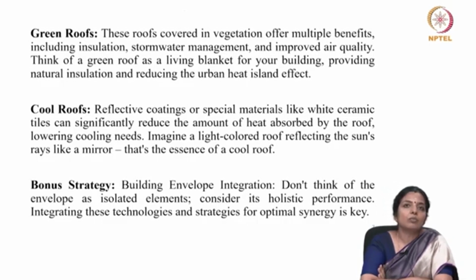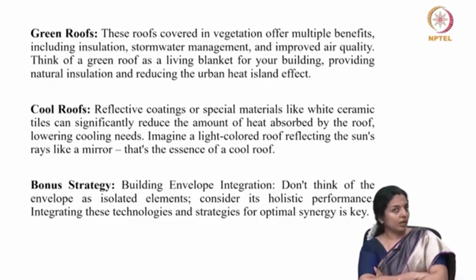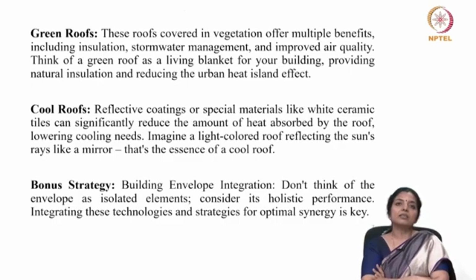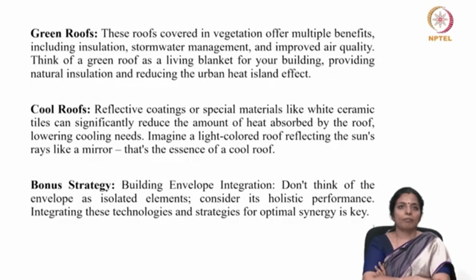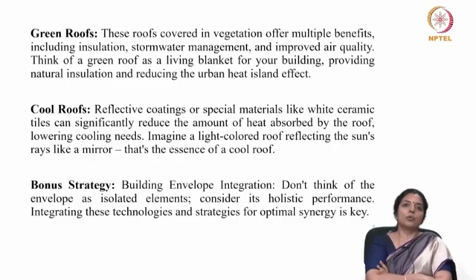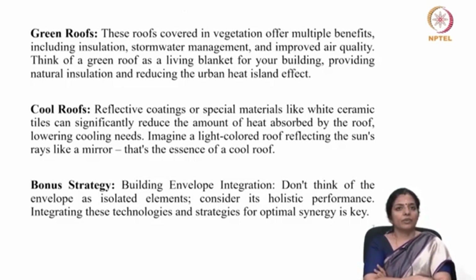The roof is one of the envelope elements through which maximum solar radiation penetrates inside. The intensity of solar radiation on a horizontal roof is much higher than that on the walls. Having green roofs provides insulation. However, one must take care of stormwater management through the green roof.